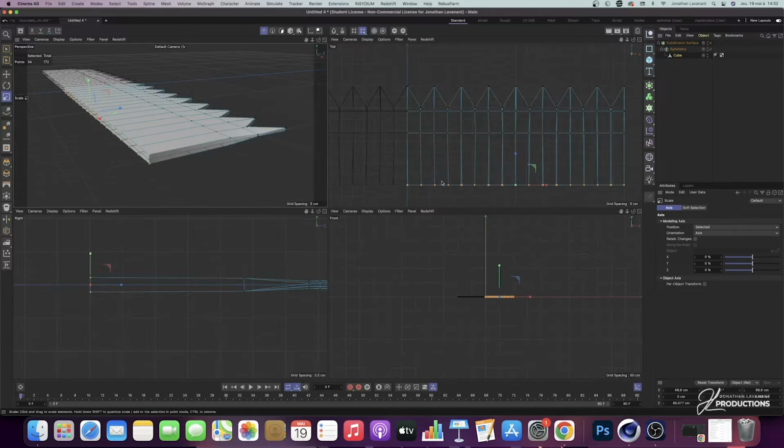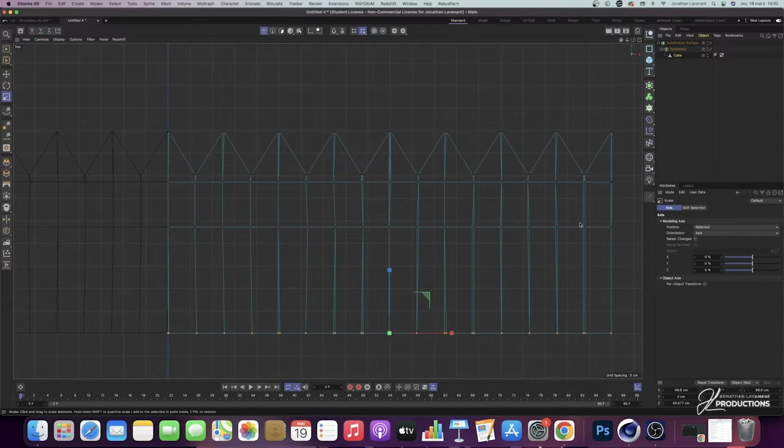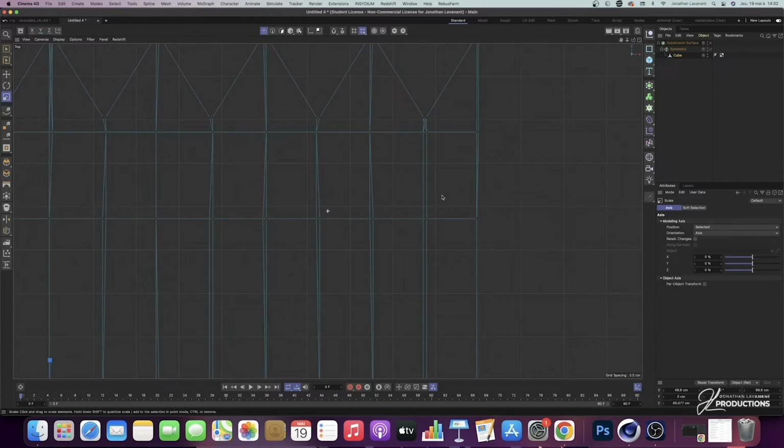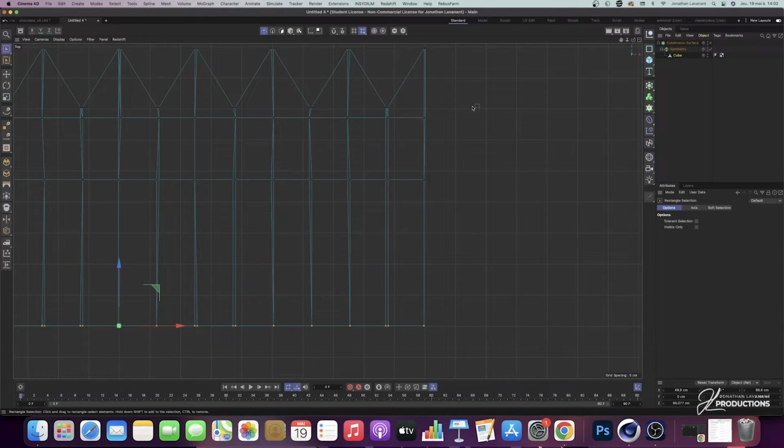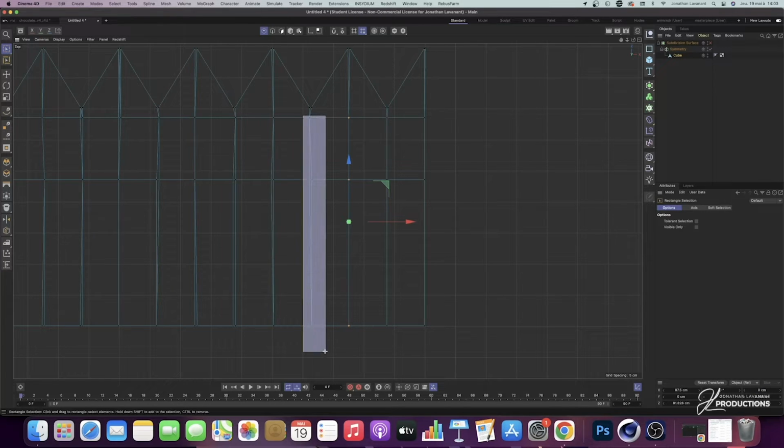So now I'm going to get back into top view here, and I'm going to be able to reset all the points to 0. So for that, I will select it here. I selected my points. Here, you click here on the small coordinates, here on the size in X, instead of 0.2 or 0.4. Sometimes you have to reset to 0. So here I come to select my points. I put to 0. I do the same here. I put to 0, and I will do the same all along the geometry.